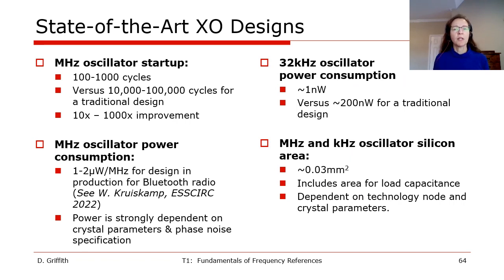So now I'll summarize the state of the art for crystal oscillator designs. For megahertz oscillators, the startup time is between 100 to 1,000 cycles, which is 10 to 1,000x improvement over the traditional design that was common around 10 years ago.